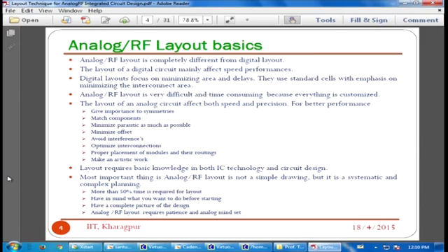For high speed operation, sometimes the ISI problem will come, because a rectangular or square wave pulse contains higher order harmonics, meaning higher frequency components. So RC parasitics will come and act as a low pass filter, so the higher frequency components will not pass. That's why it will interfere with the adjacent symbols. That is what we call the ISI problem, inter-symbol interference. Generally, it degrades the bit error performance of the whole system.